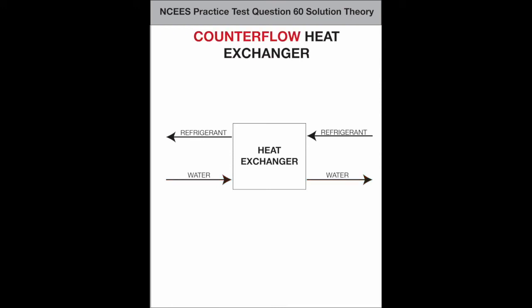Hence, counterflow. Because these are two different fluids with different properties, such as density, both the temperature and enthalpy changes don't match. The energy flow in the massless unit of BTU per hour does match. Energy flow that goes out of here must go into here.